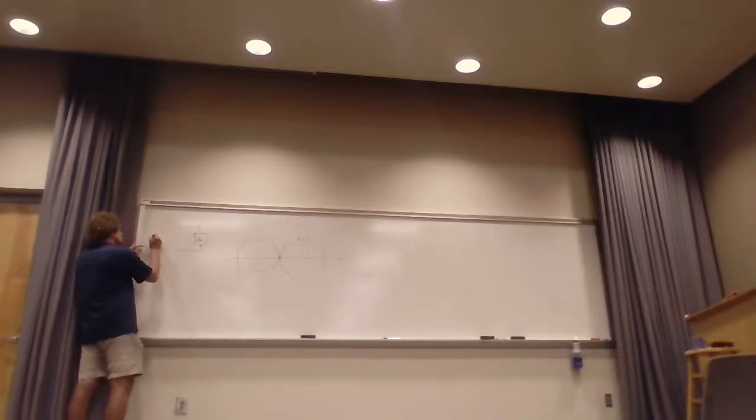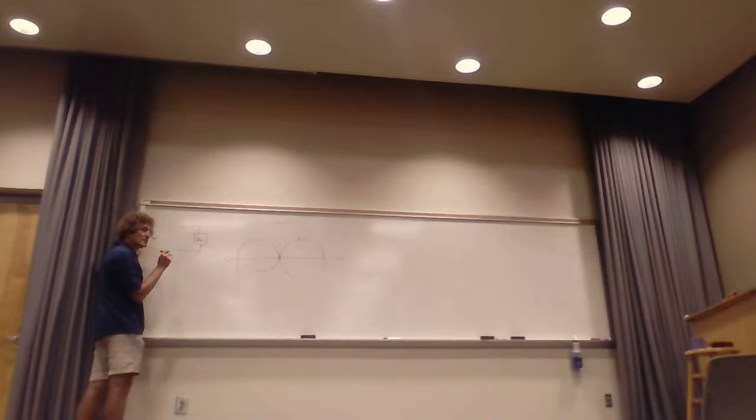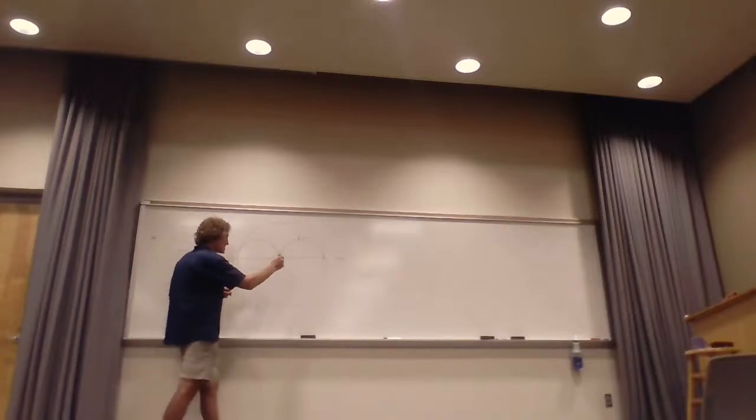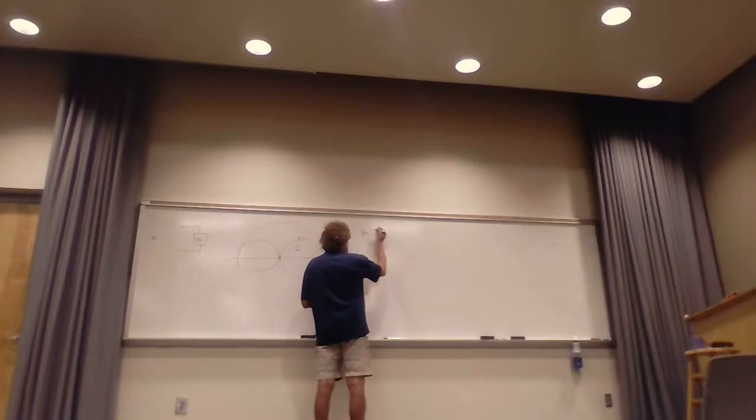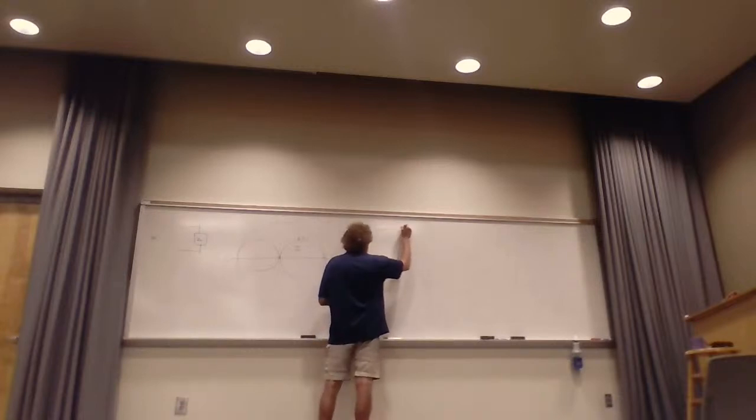and a characteristic impedance and we want to match it, our choices are this. The first one is if the normalized load falls inside the 1 circle. So this is case 1. The normalized impedance is going to be inside the 1 circle.